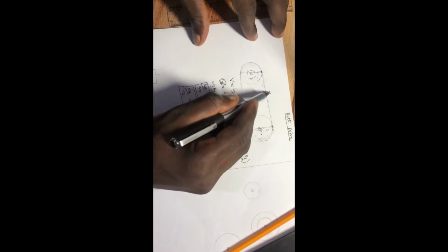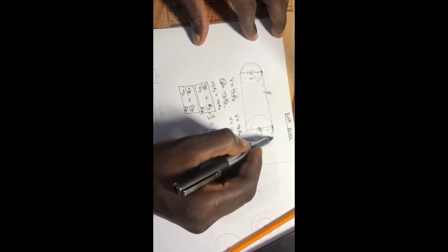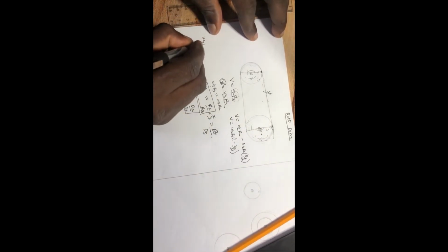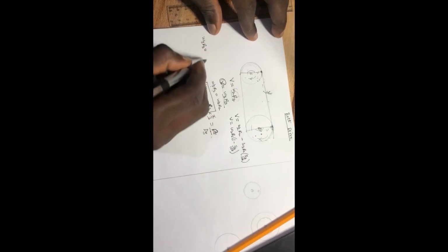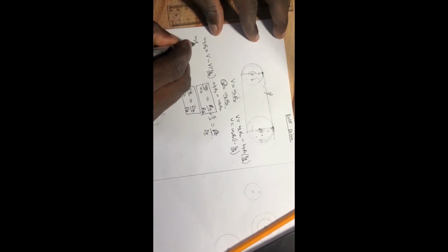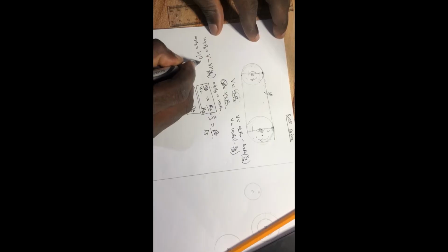So you're going to take the component of the velocity that is used in slipping when it's trying to turn this one around. So omega 3 R3 will be equal to what? The velocity coming minus the component that goes into slipping. You understand that? That means our omega 3 R3 will be equal to velocity into brackets 1 minus S3 on 100.